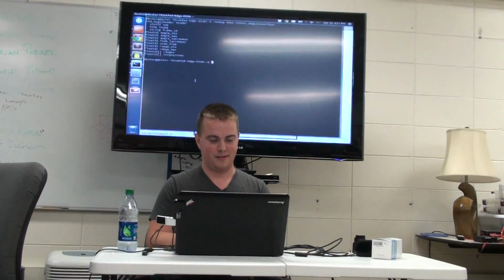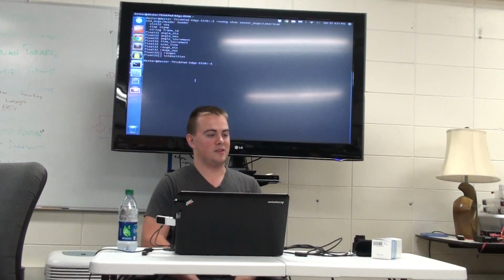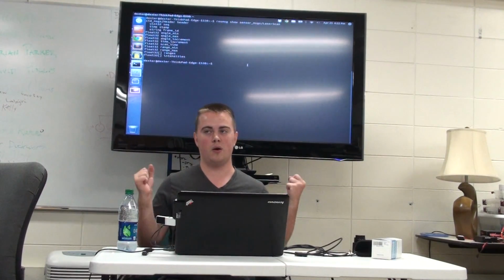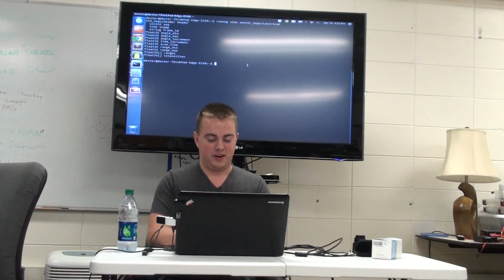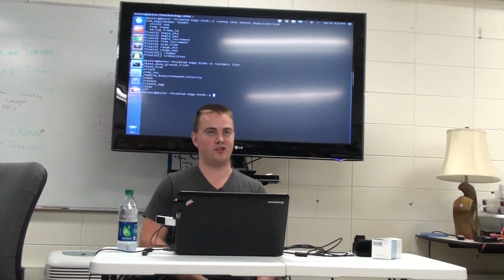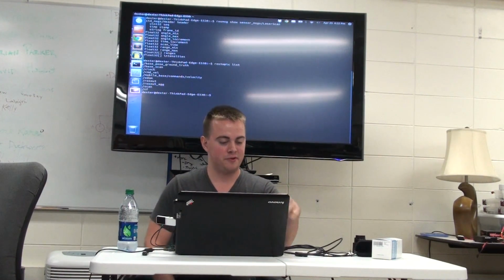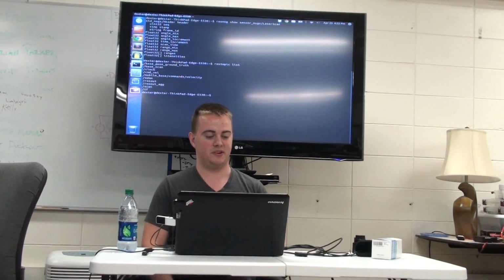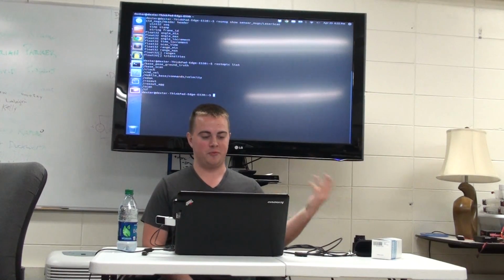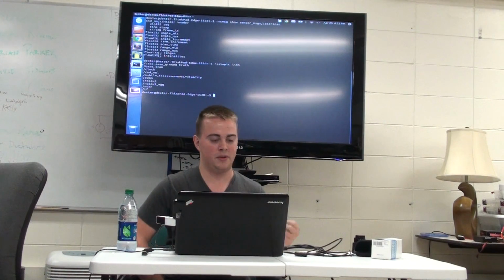While we're here, though, other things happening, let's actually try seeing some stuff. Let's say we want to know what's happening right now. So we have this up. First of all, we want to know what topics there are. We can do ROS topic list, and that gives us a list of all the topics that are currently being published or listened on. So we have base pose ground truth, which is a simulation thing, base scan, which is the scan data coming from the simulation. We have clock, which is just a clock tick used to synchronize things.